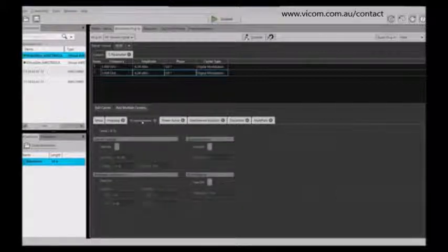So we also give you the capability of turning on some IQ impairments, and this is very useful for receiver testing, such that you can build your waveform such that it will give you the worst case condition for your particular receiver requirements. And so you can swap the IQ, see if your receiver can handle swapped IQ patterns.